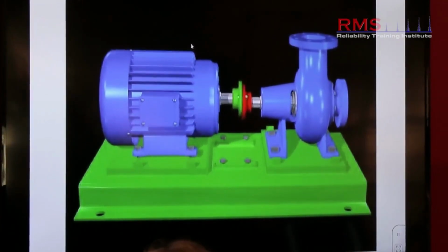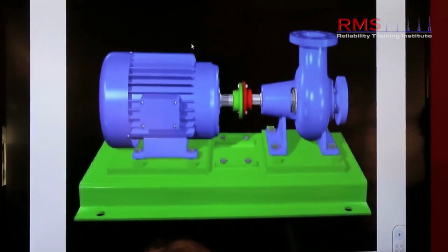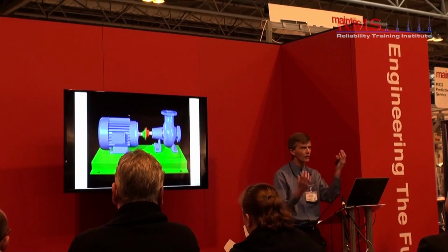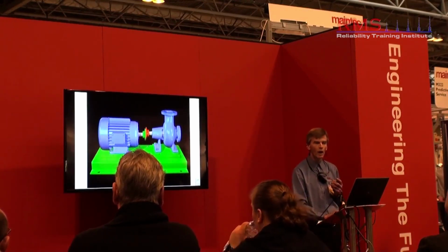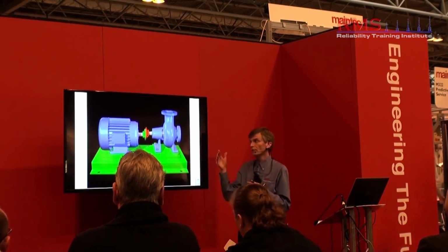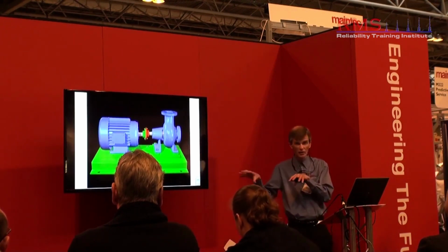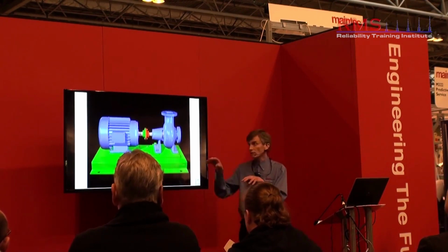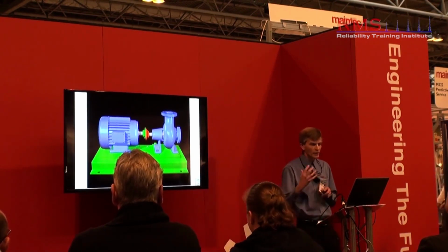I think a key point to think about with vibration is a couple of things here. Visually is the forces. Think about the forces. The forces here are radially being generated. If I place a sensor radially around this machine, I will measure those forces. Obviously very exaggerated, but if the machine were misaligned like this, that machine is trying to do this in real operation, and that's going to destroy the shaft bearings, the shaft seals, and so forth. So we have to think about the forces.